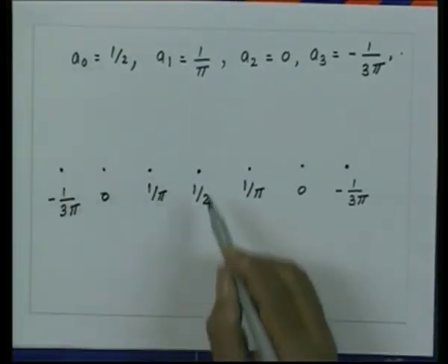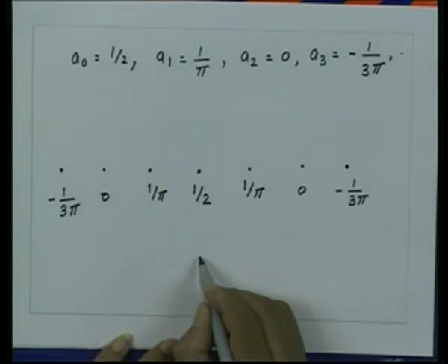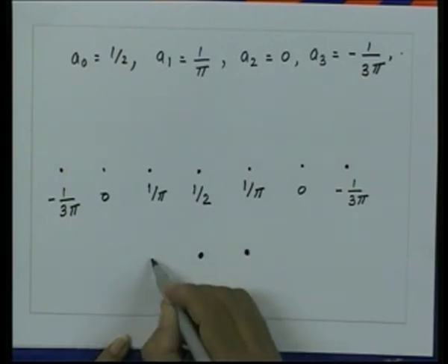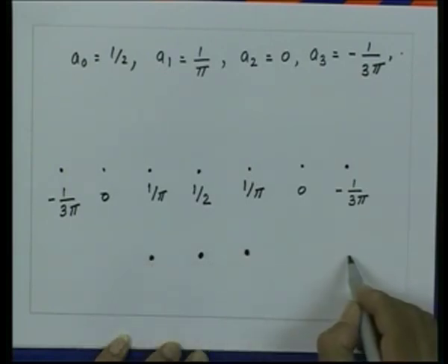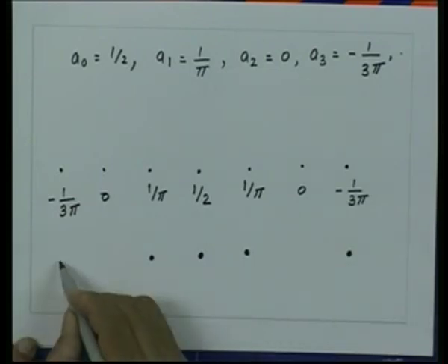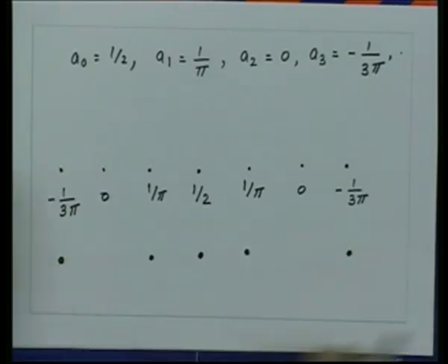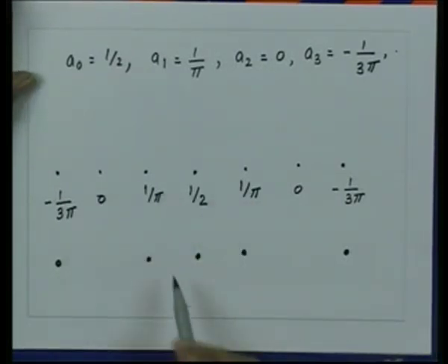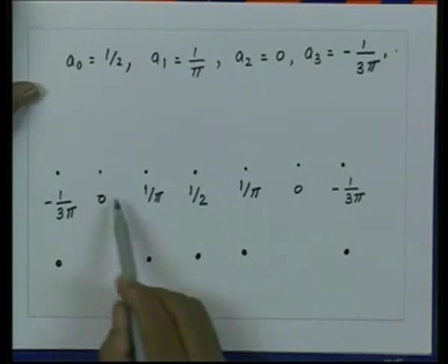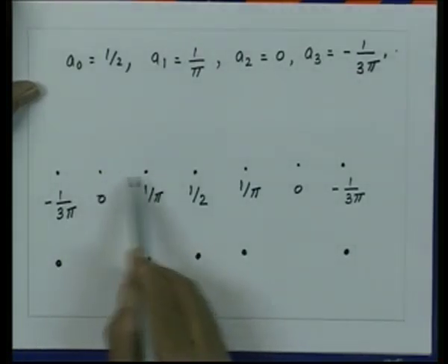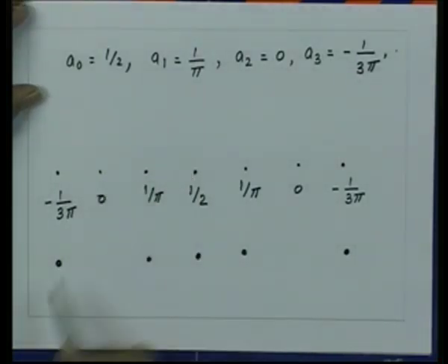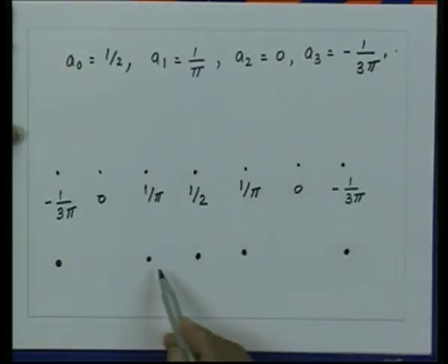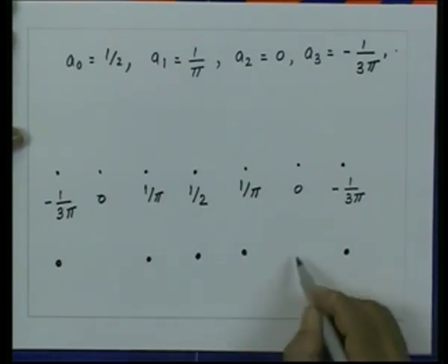So, the array essentially which we get, which is 5 element, will be this. This is one element, this is another element, this is another element, then this element and this element. Though we started initially with an array which is a uniform array, where the spacing between the adjacent elements was the same, which was lambda by 2, in the synthesis process we essentially end up with an array which is non-uniform, because this current is now 0.